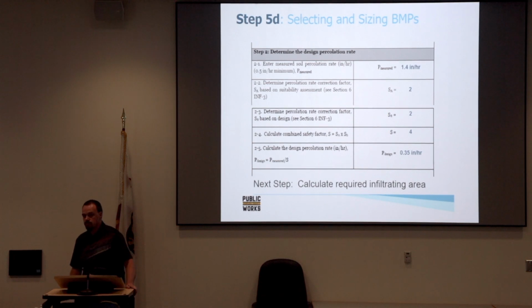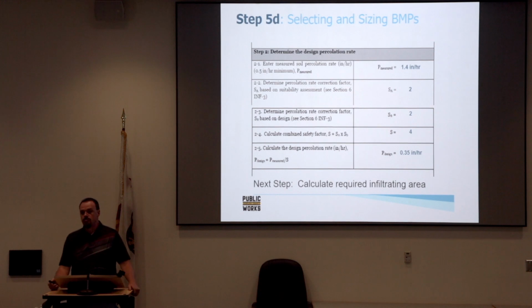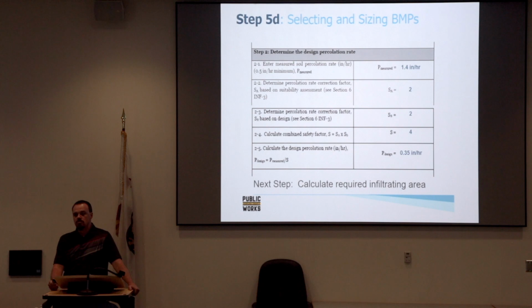Now, during the review of the geotechnical reports, have you come up with an acceptable minimum depth for your borings to get all these readings? Because I've seen them down to 50 feet for liquefaction, some are 10 or 15. And now with the groundwater requirements and the stormwater infiltration requirements.